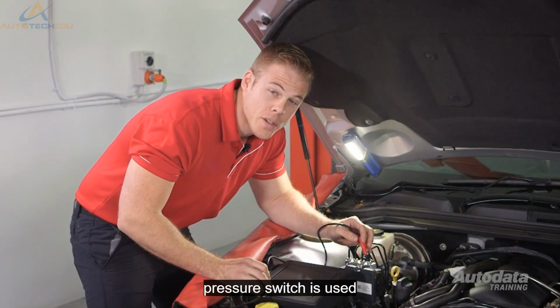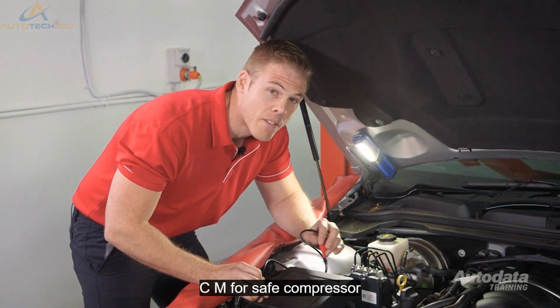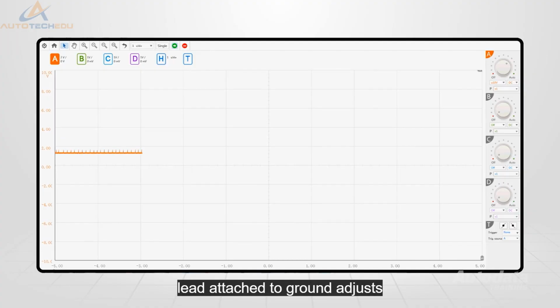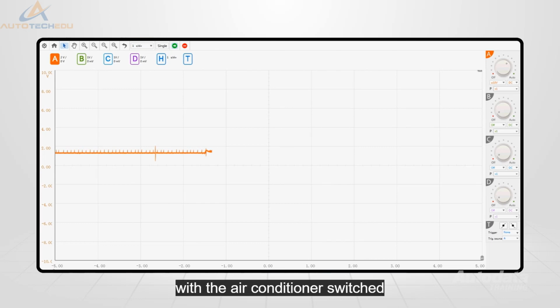The AC pressure switch is used to relay the pressure within the system to the ECM for safe compressor operation. Back probe the sample lead at the signal circuit and the black lead attached to ground. Adjust the Y-axis to 10 volts and the X to 1 second. For this vehicle, on a 22-degree day with the air conditioner switched off, our trace looks like this.